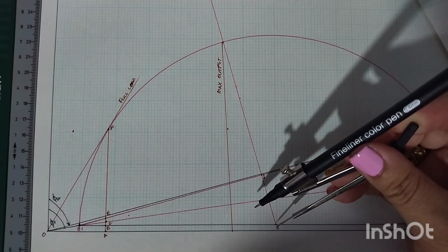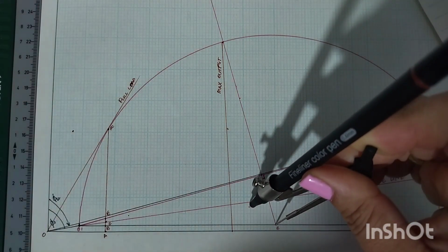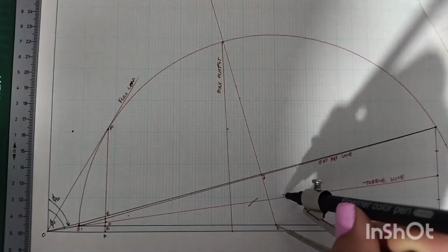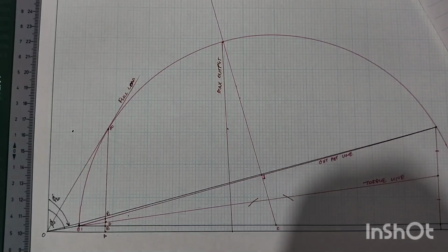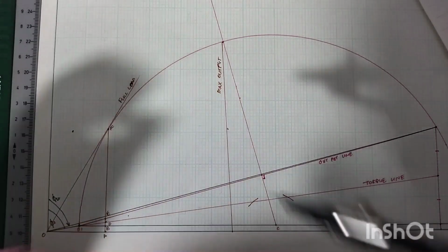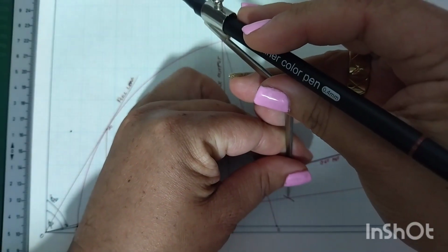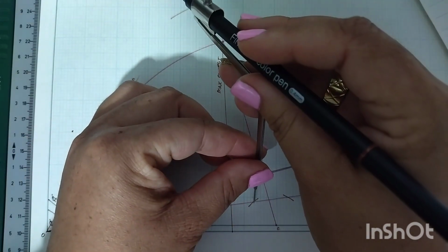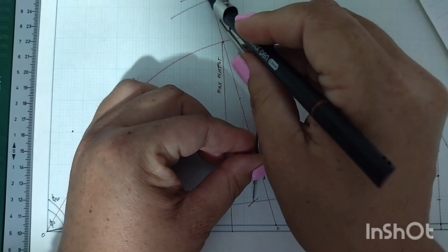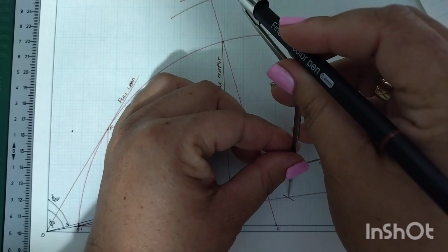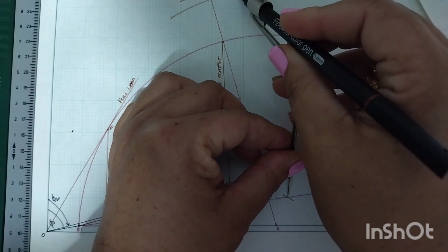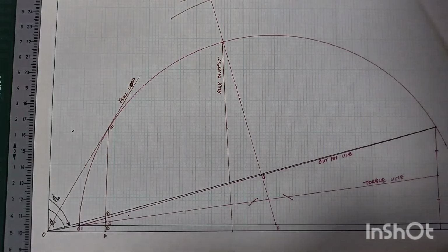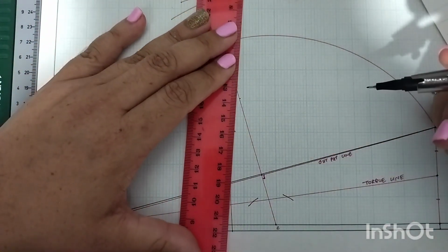And now, this is very important. For max torque, you're going to take any radius and make 2 marks on your torque line. Where these markings intersect your torque line, you're going to use a larger radius to make again 2 markings on your graph paper. And where those 2 markings intersect, I didn't quite get it right the first time, so I had to go back to get a clear point of intersection. From there, perpendicular to your horizontal axis, that would be the conditions for maximum torque.